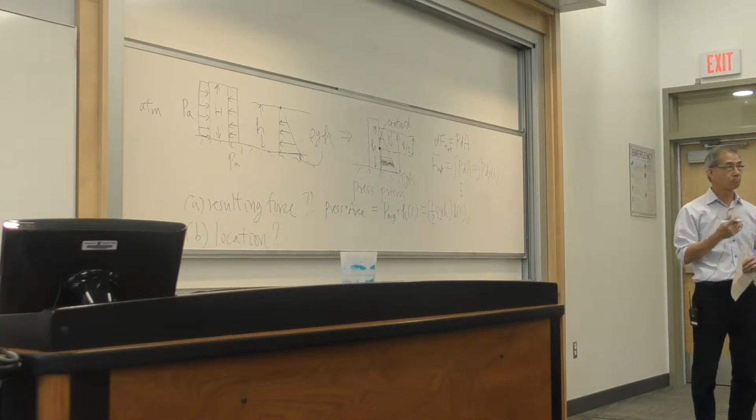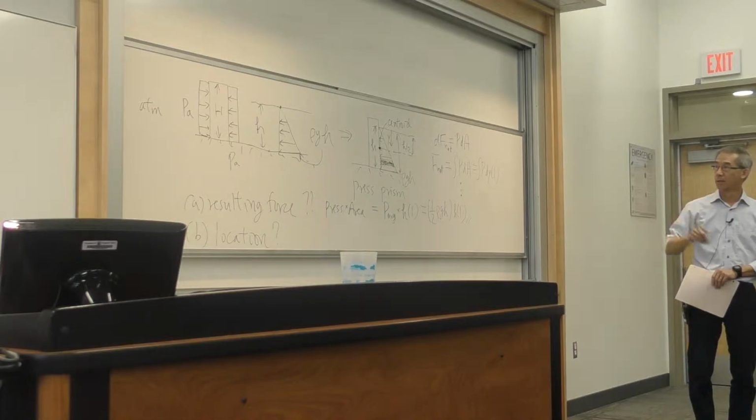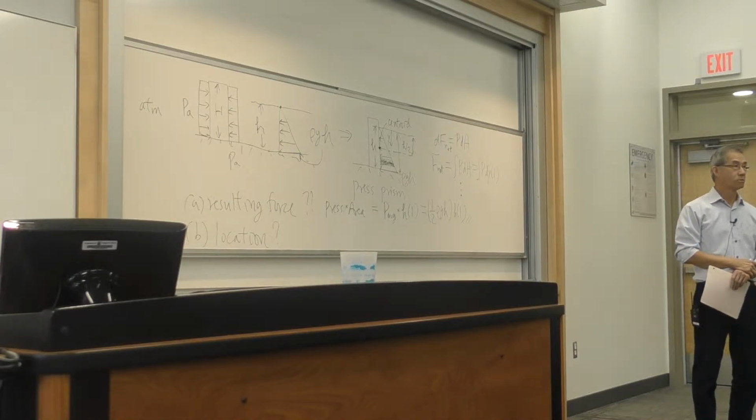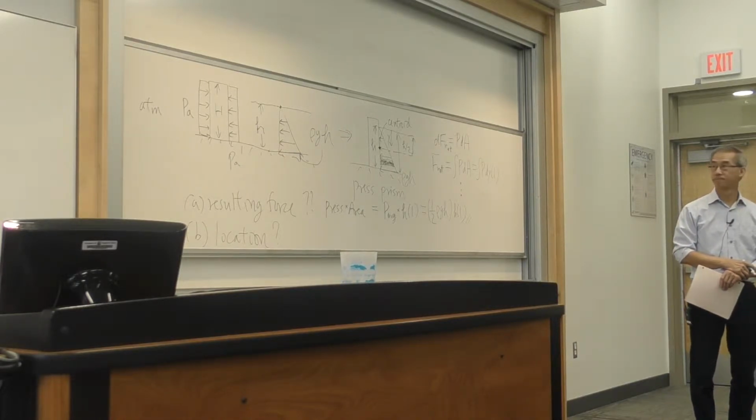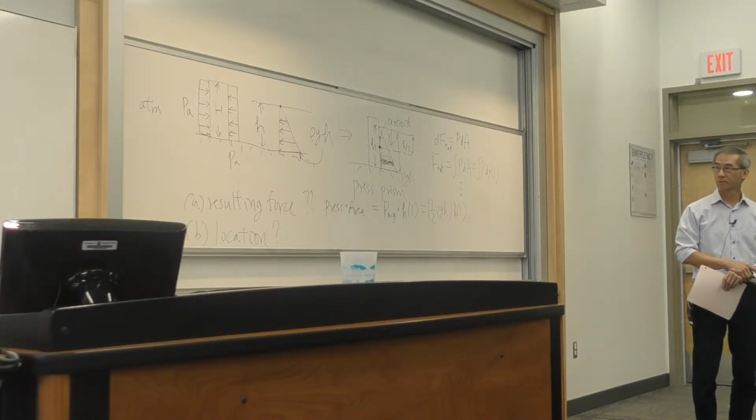So that's one of the two questions answered. The resultant force is average pressure. What do I mean by average? Well, turned out to be half rho gh, depth times an area. Question on that? A step at a time, we're going to build so that I can use this to do the example problem to follow annual homework.